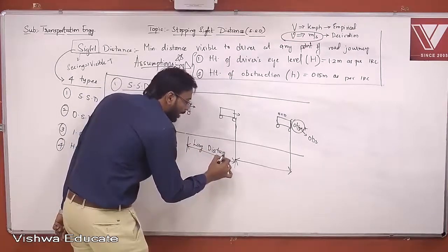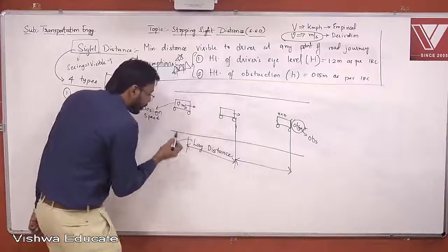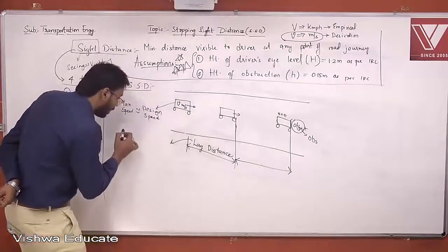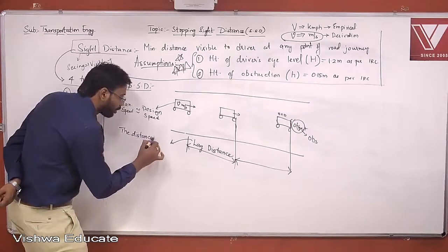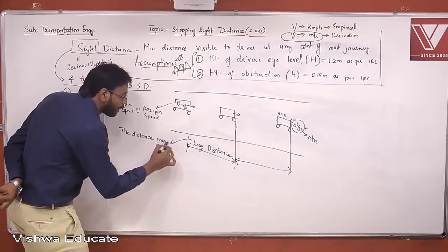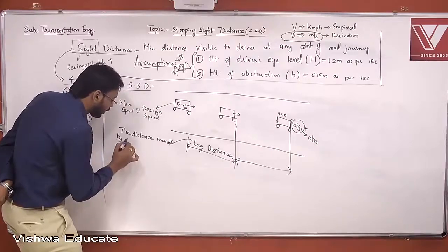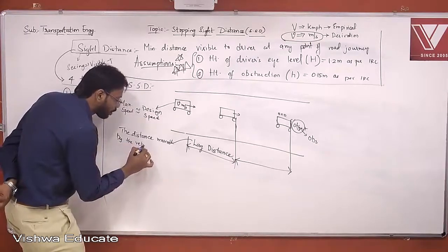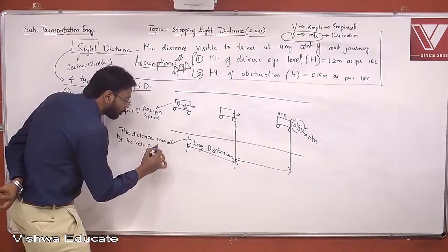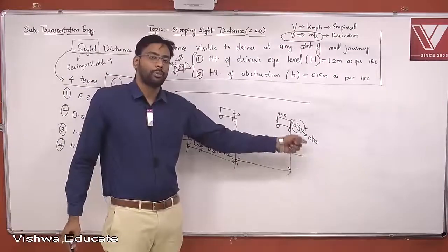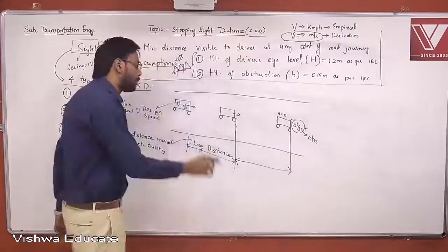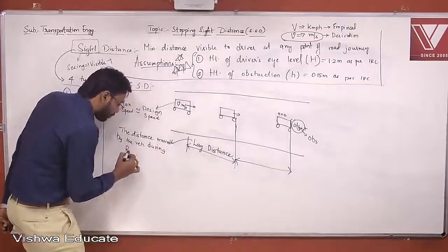So what is lag distance? How can I define it? The distance moved by the vehicle during your thinking time, whether this is an obstruction or not. And that time is called reaction time.